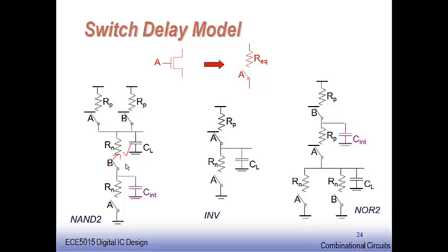If I go for shorting this with a logic 1 here because it's an NMOS device, and I give a 0 here, I am not going to have this NMOS on, then I am not going to find any discharging path. And similarly, when you have 1 given here, this would be shorted, whereas this device is not going to be on. With this device on, whatever nodal charge I had in this internal capacitance will go down to the ground.